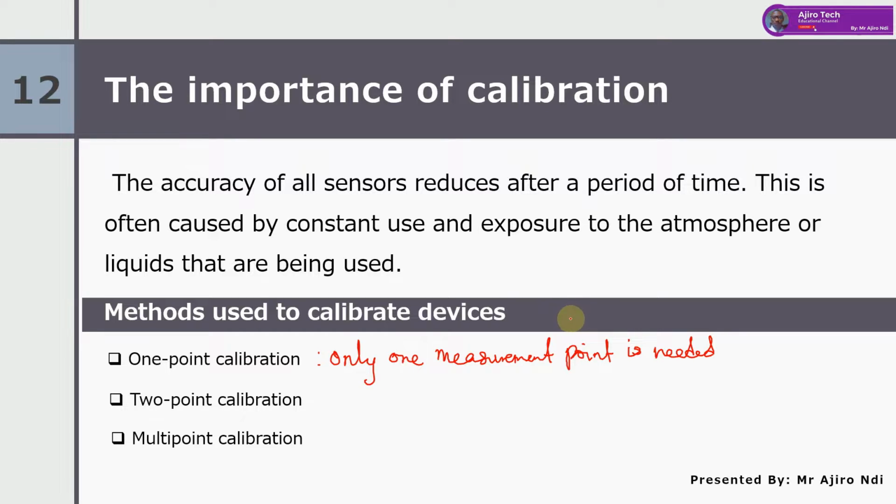This type of calibration is often needed for sensors which are constantly used at very high temperatures, after some loss of accuracy. Accuracy can be checked by doing a 1-point calibration every so often and comparing the result with the previous calibration.